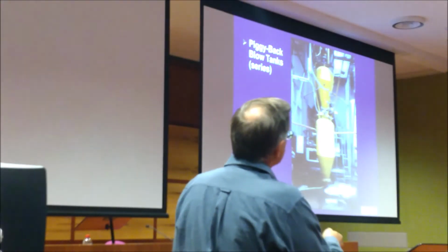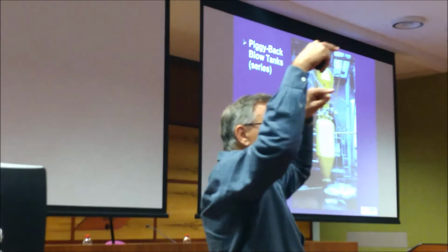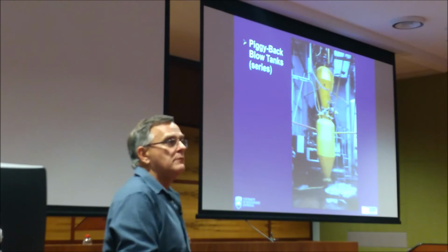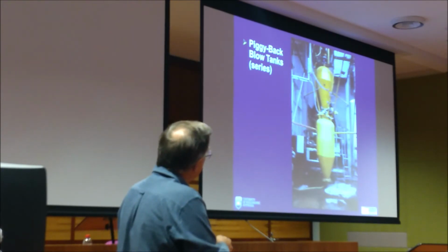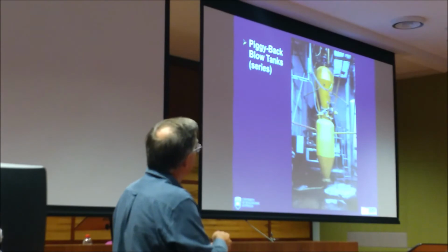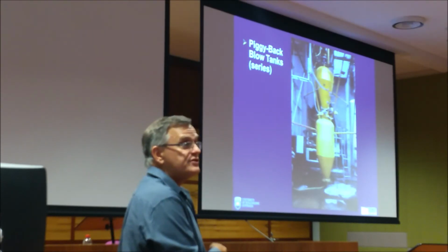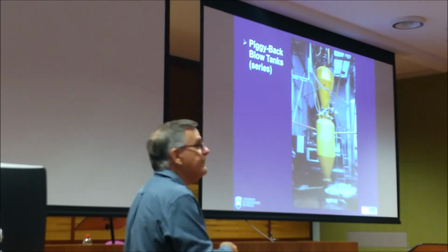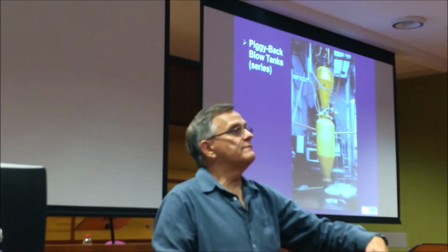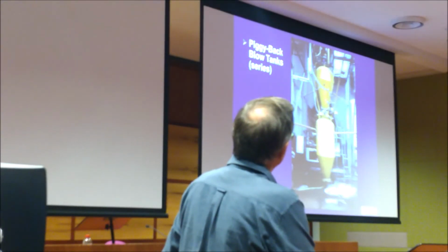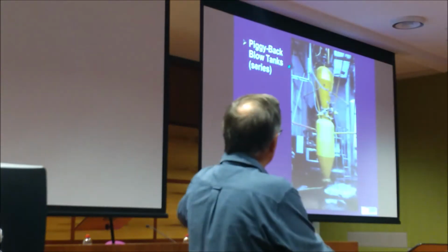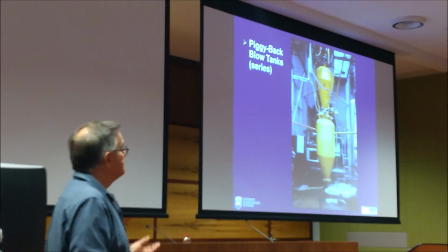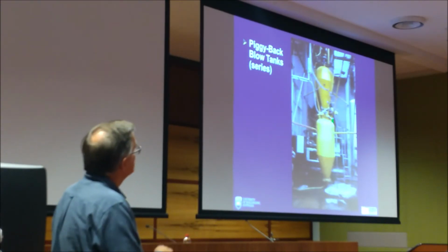So that pipeline runs across here a couple of 100 metres into the boiler, goes around, got multiple feed points. And so this is running 100% all the time. So when the level in here drops down, this valve is shut, this one has been refilled under atmospheric conditions. We shut this, pre-pressurise, we balance the pressures, we open the valve, and that powder then drops into the main feeding vessel. And it refills the blow tank, close it off again, we vent this, refill it, vent it again. Just like an airlock system. And so while we're filling, this thing's continually feeding at 100%.